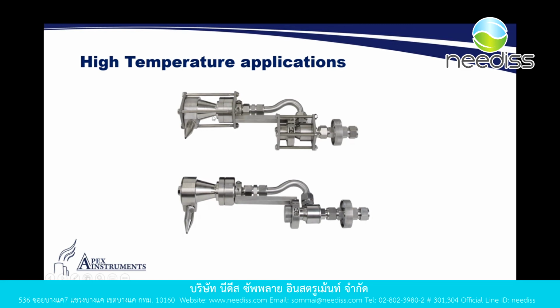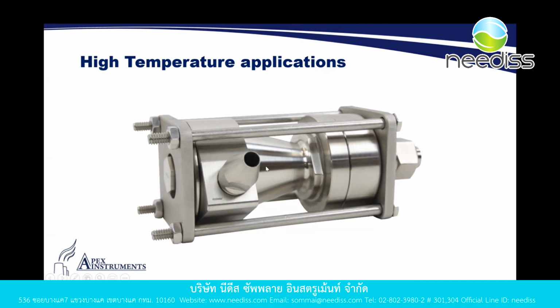So even the cyclone itself can take even increased high temperatures for your sampling needs, because we know that many stacks are quite challenging when it comes to moisture, temperature, acid gases, things like that. So this is important. Here's an image of an individual PM10 cyclone with that same non-threaded bolt design for the high temperature applications. So we can also do that for the individual PM sizes if that was something that you were in need of for your customer.